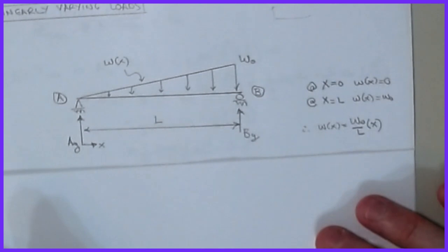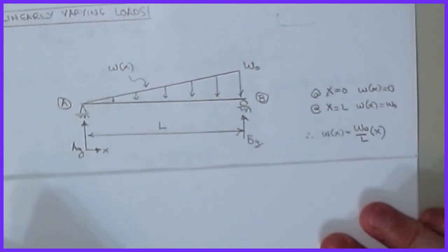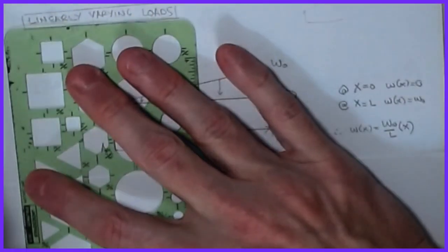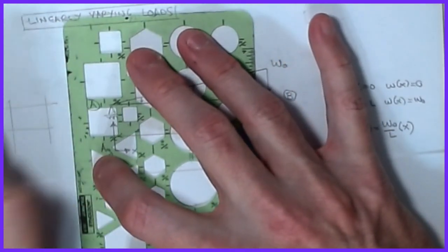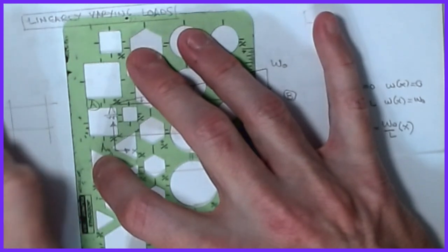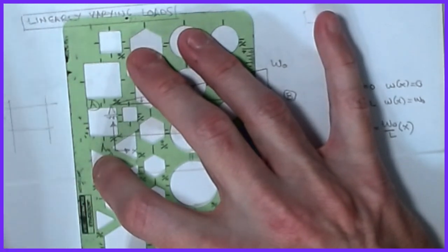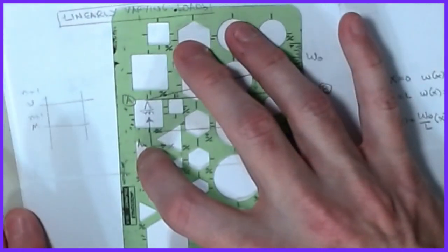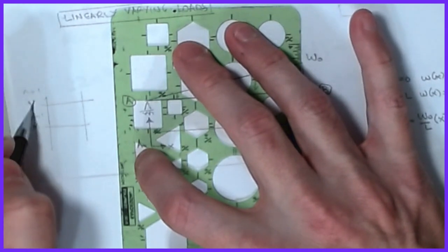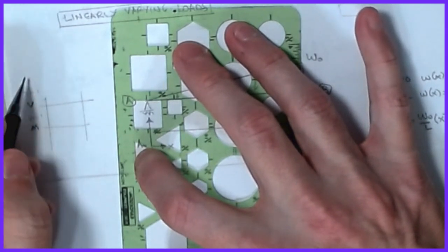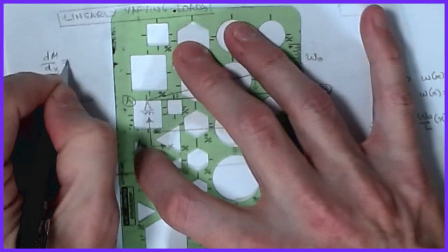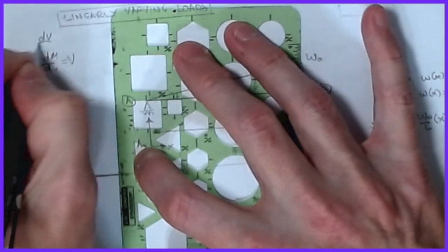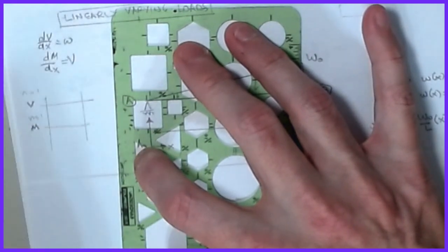Now, as you remember when we were looking at the shear moment diagrams, when we draw our beam and we look at our shear and our moment, we gain an order every time we move down the picture. We always draw the shear first, we draw the moment second, and the order of our diagram changes because remember that dM/dx is related to V, and that dV/dx is related to the load, or something kind of like that.